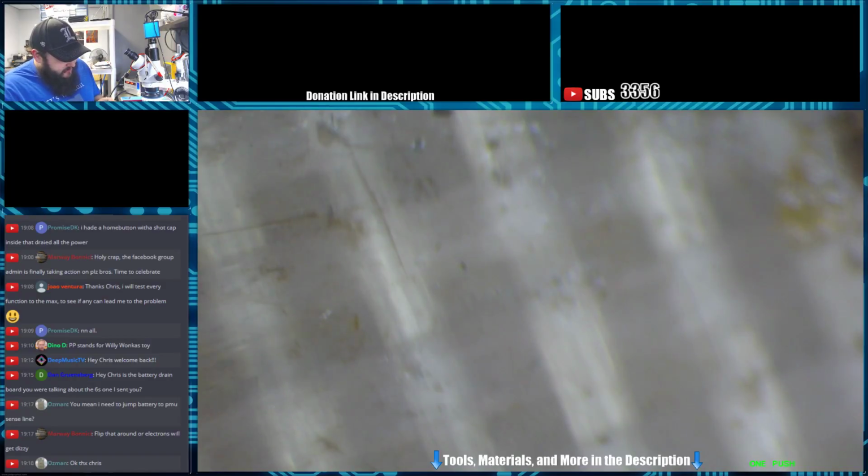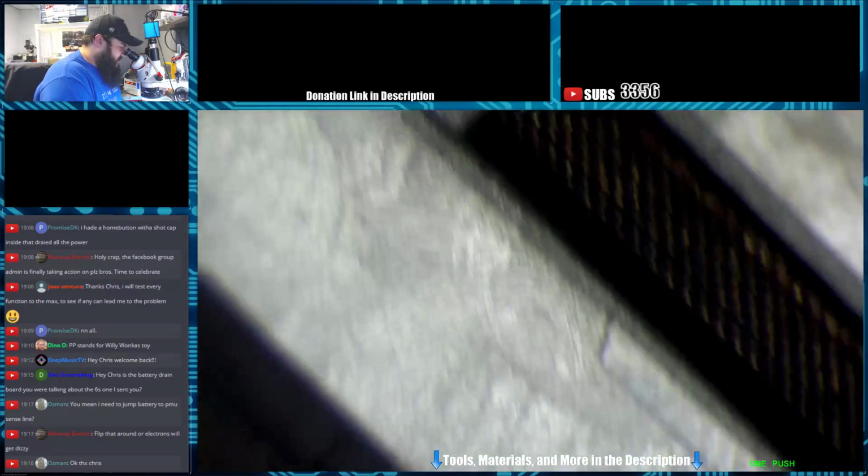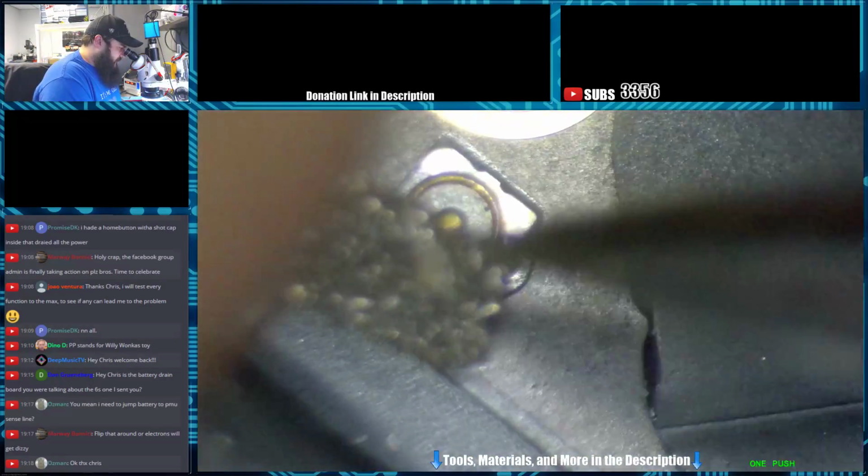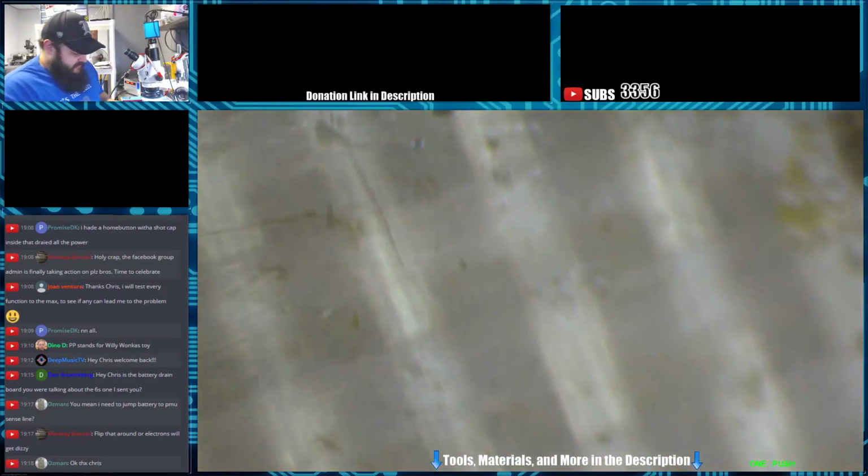On a secondary note, the iPhone 7 boot looping issue is becoming more prominent. We're seeing quite a few more with either boot looping or lag issues from the audio IC or baseband PMIC. So if you have some that come in where they loop and they give you error 4013, there's a possibility that that's going to be baseband PMIC. If they come in and they are slow booting, or they loop sometimes and you have no microphone or audio issues, that's most likely going to be your audio IC, so you can check that out too.